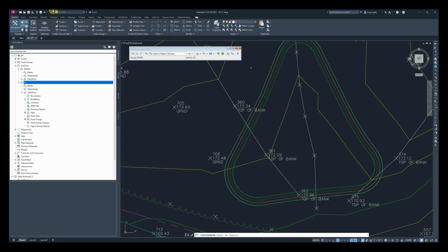Now what we want to do is create an infill. We just did create grading before from our grade creations toolbar. Now let's go down to create infill. Again, we can pick around the same spot inside this area. Let's click that, and then press enter. And we see we have some additional lines being drawn in for our infill.